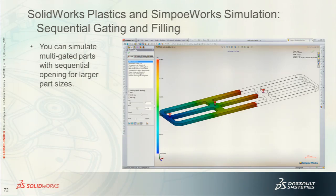You can do sequential gating and filling where, say you have a long part and you have 3 separate gates. What happens is the first gate starts the fill process. As the wavefront goes past the second gate, material will start flowing from that, and then as you get to the third one, you will be able to replicate this process.